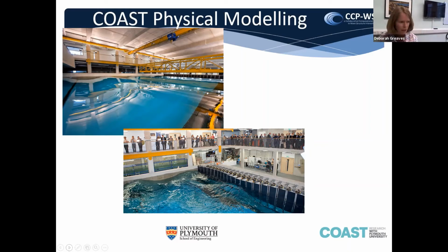So we have a very nice coast lab. We have a couple of wave basins and some flumes. We do lots of experiments, and this is our large ocean basin. It's like a swimming pool, really. It's 35 meters long and 15.5 meters wide, full depth of 3 meters, has individually controlled wave paddles, so we can generate any sort of complex waveform. It also has a current generation system, and just now we have investment in a wind generation system as well that will go over the waves, which will enable us to do all sorts of further exciting and complex experiments. And we're particularly interested in floating offshore wind and the combined loading there.